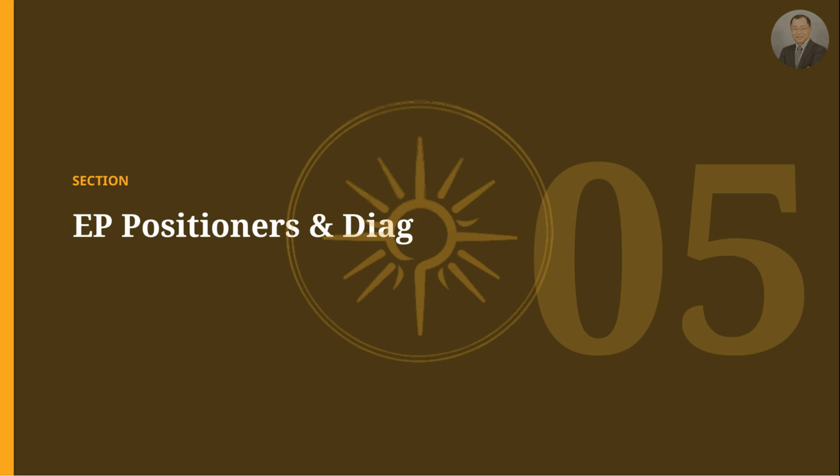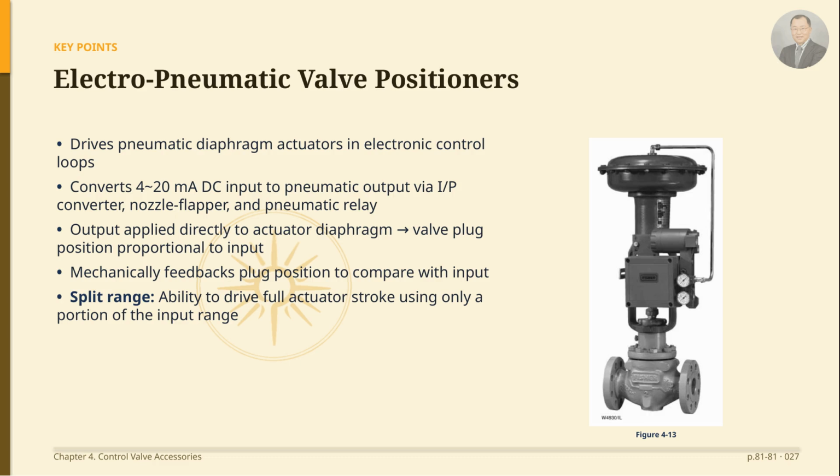Next, we turn to EP positioners and diagram. Electropneumatic positioners are used in electronic control loops to operate pneumatic diaphragm control valve actuators. They receive a DC input signal from 4 to 20 milliamperes and convert it into a pneumatic output signal using an I/P converter, nozzle-flapper, and pneumatic relay.